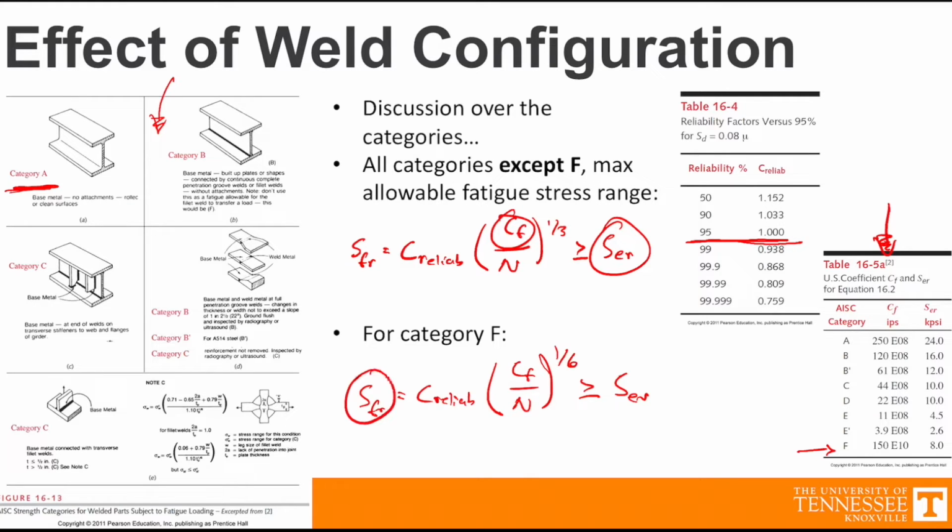And so it makes it really easy when we want to use this value to calculate the factor of safety. All we need to do is plug it into the following equation for welds. This is going to be SFR over the applied stress range. Like I said, for dynamically loaded welds, it is all dependent on that stress range, which makes this so nice and simple.